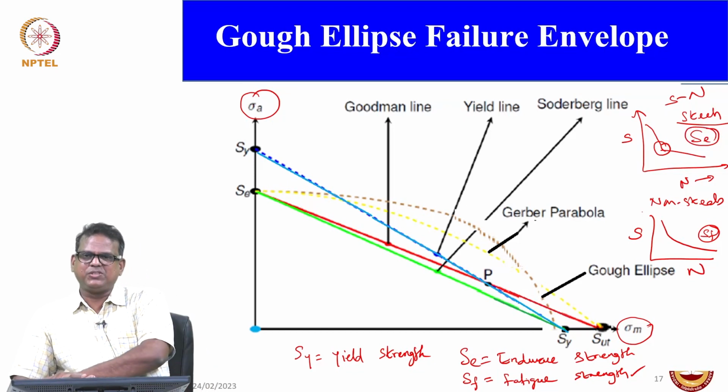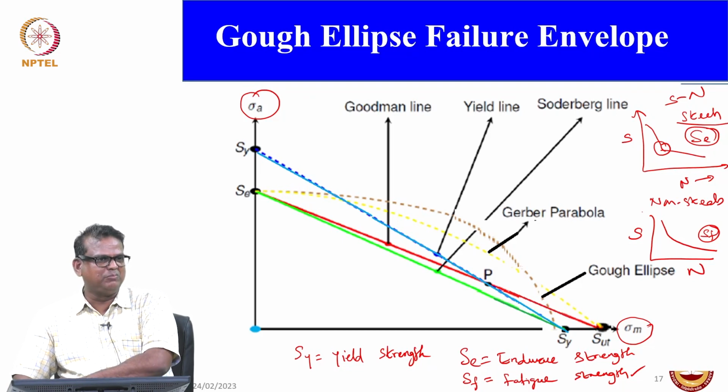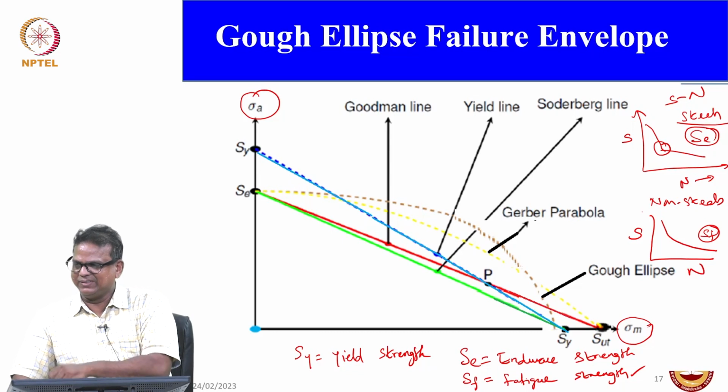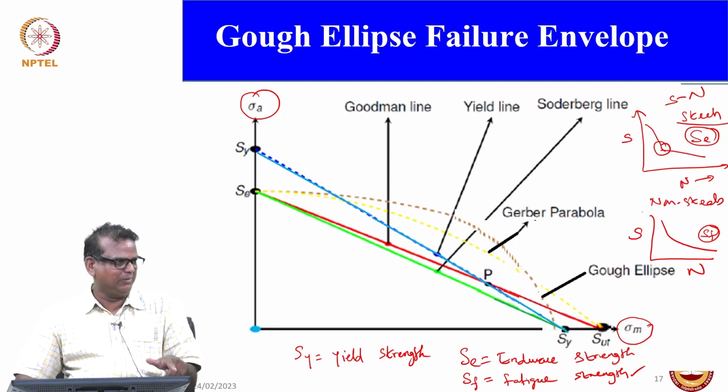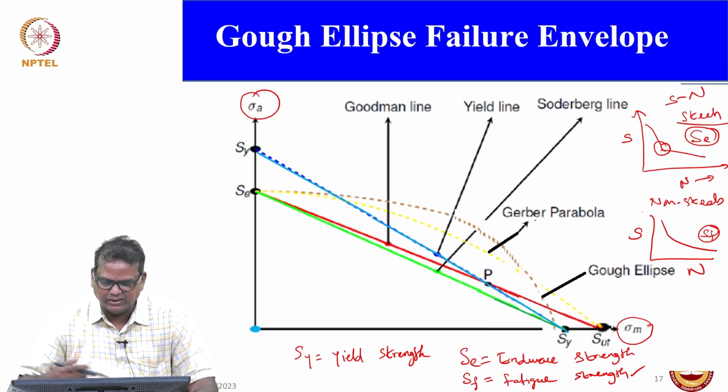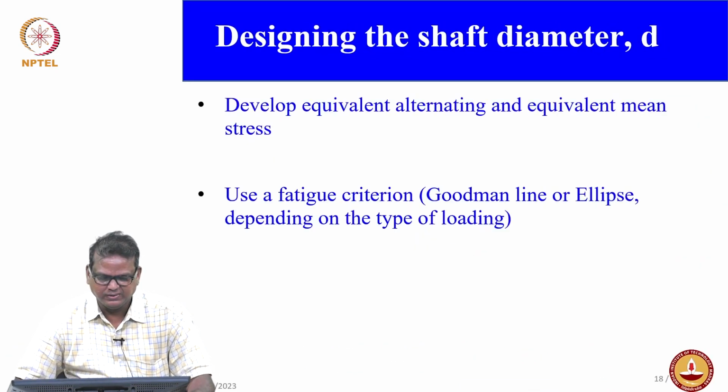Okay. Generally, which one is preferred: the Goodman equation, the modified Goodman equation, or the Soderberg equation for shaft design? It depends on the material, whether it is steel, and whether it is a ductile material or a brittle material. Based on that, things will change. So, you need to brush up on your failure theories.